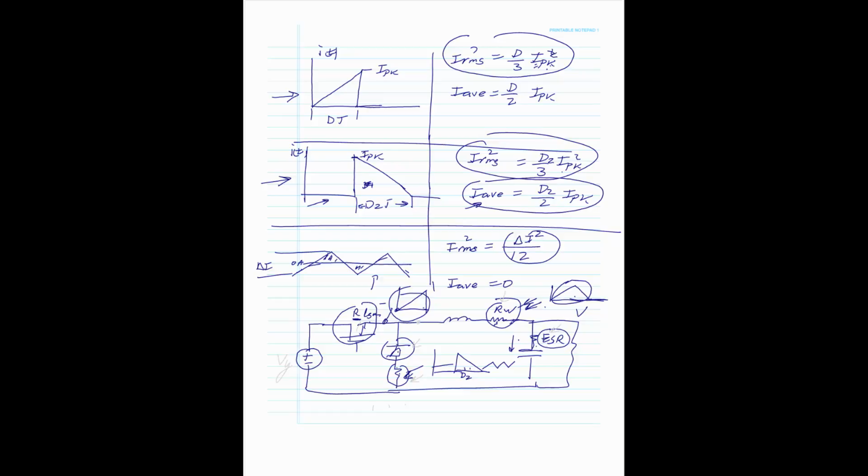So now we have that power dissipation here, we have it here, we have it here, we have it here, and we have it here. So that's all the power losses. Over the power out is the efficiency. This method is very, very simple to get to any complicated system. All you need to know is what are the waveforms.